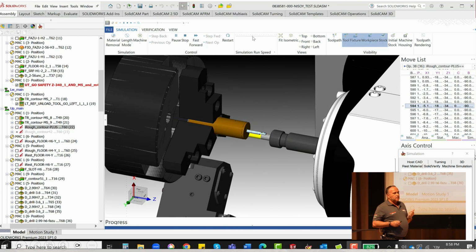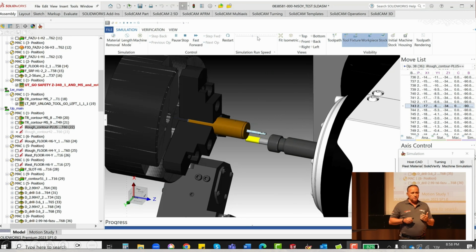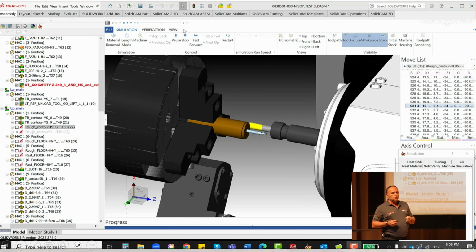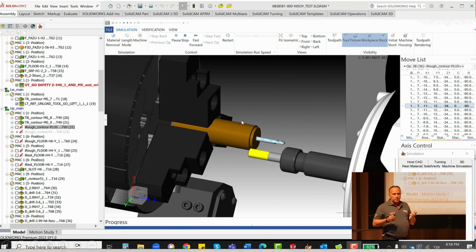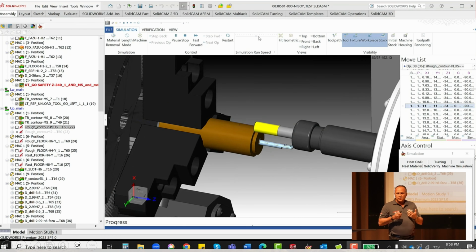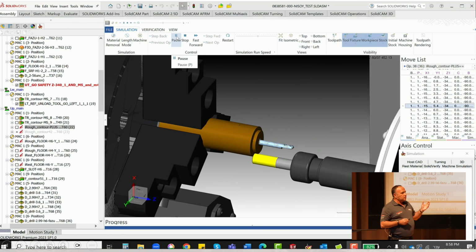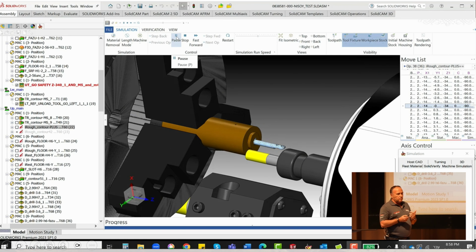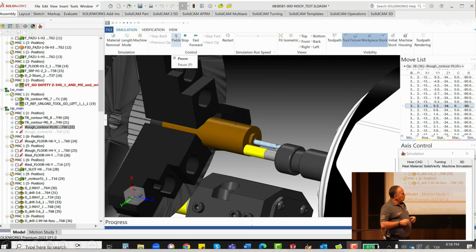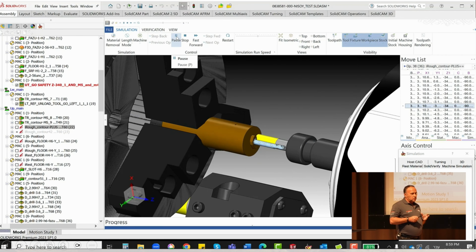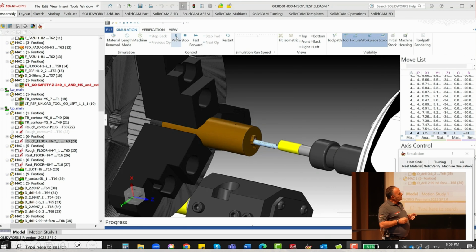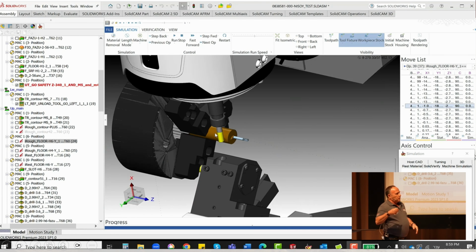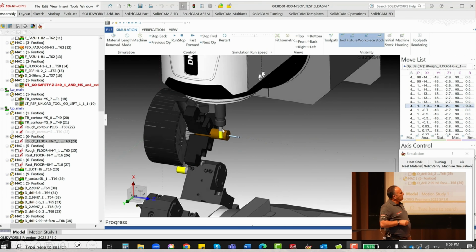And what is the reason that we use iMachining in mill turn? It's not just to reduce time, this is obvious, but also to keep a suitable process. It's very important in a part like this. A very small part, we want to avoid vibration, so iMachining is perfect for this. We know there is a constant force on the tool also, and as you can see, it's iMachining from, we call it, the face, and after it,